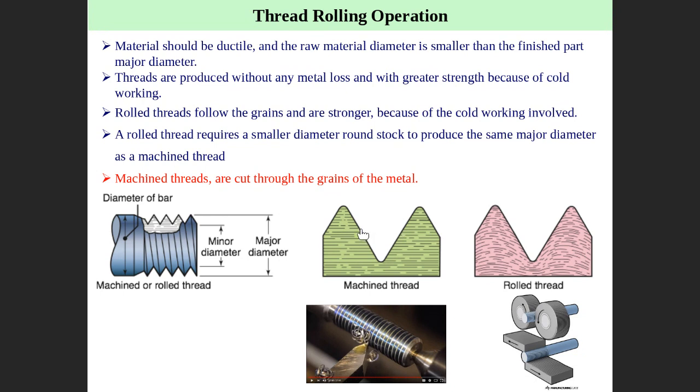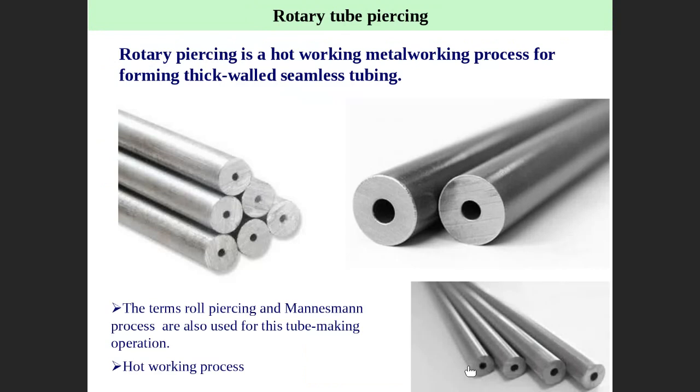The highest precision and accuracy can be achieved by machining, because rolling is metal forming. You have to flow the material, you start with a smaller diameter, and then as the material flows it finally reaches the exact dimension. Actually, it is very difficult to adjust the exact dimension. This is always the problem facing deformation by the rolling process, right?